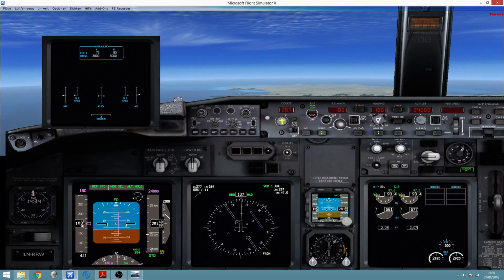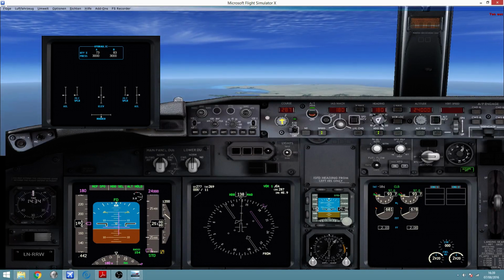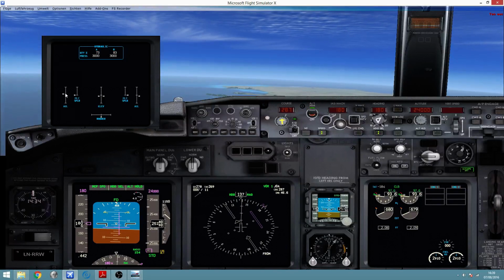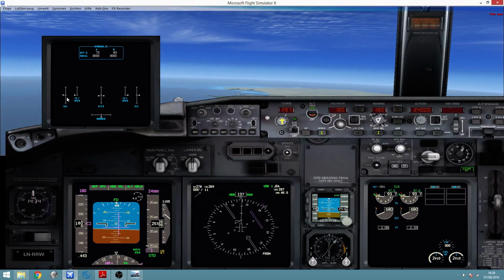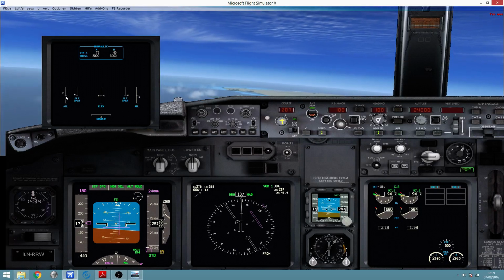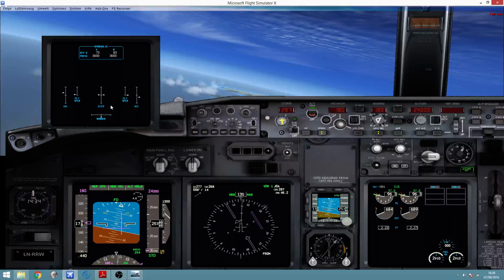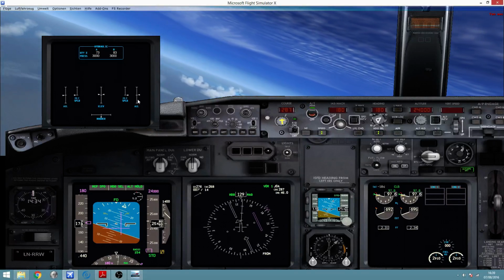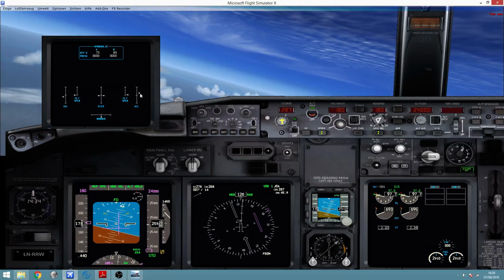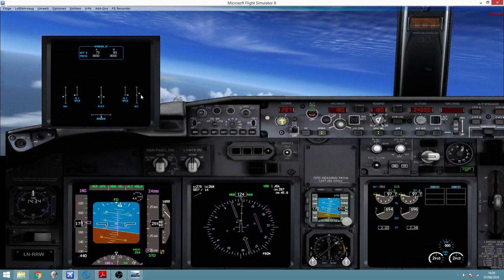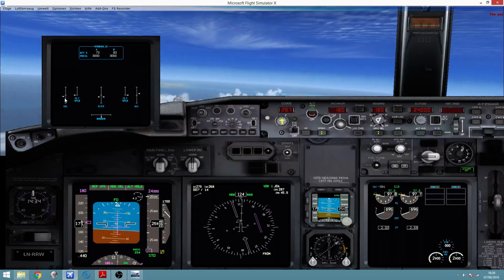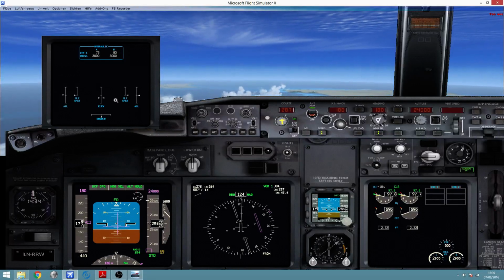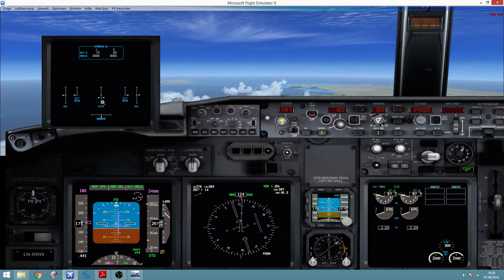So if I pressed Shift 9 and I could see this window, here I'll have a reading of the position of the controls. And you can see that if, for example, I want to turn left, the left aileron is moving up while the right aileron is moving down. If I want to recover the turn, I turn right by moving up the right aileron and down the left aileron. And well, these are basically the controls of the aircraft. And the same for the elevator.